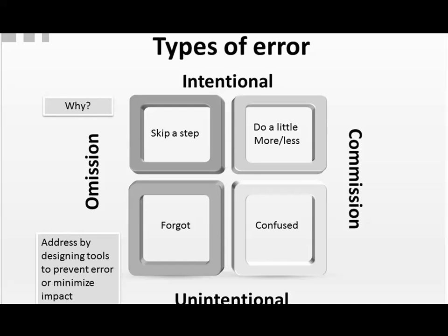The same with intentional error of commission. The set point is 85. Going after 85 could start an overheating type of reaction that could result in this type of contamination or burn or whatever. On the other hand, if I don't want you to forget to pick a sample, maybe I incorporate some type of checklist in a place where I know you won't be able to miss it. It could be even in my procedure, one step saying, collect the checklist and sign here. There are ways of doing it, or alarms, or poka-yoke. There are other things that we can incorporate here.